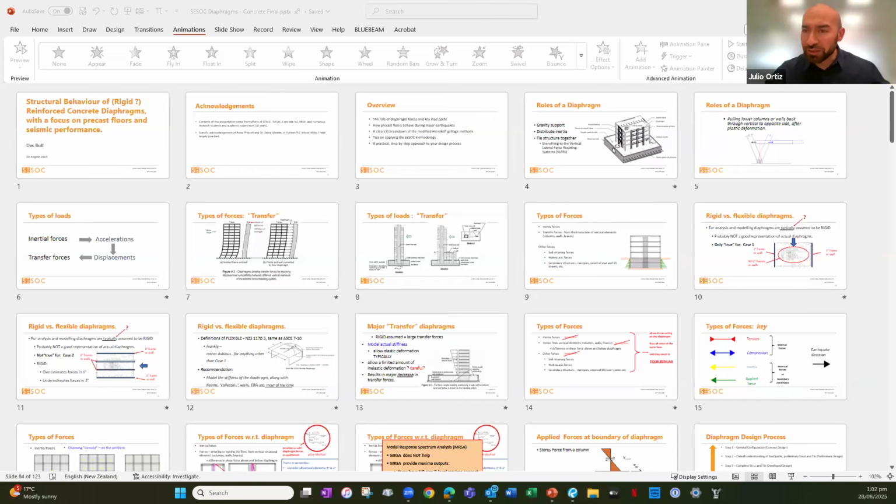Could you kindly explain whether we should consider prism strut and bottle strut in a strut and tie model? Oh, I mean, that's a whole other 116 slides. Depending on the situation, some struts will naturally form prisms, rectangular type struts, like the struts you get in a well reinforced concrete beam. But when you've got flat slabs or very deep beams, the struts tend to form bottle struts.